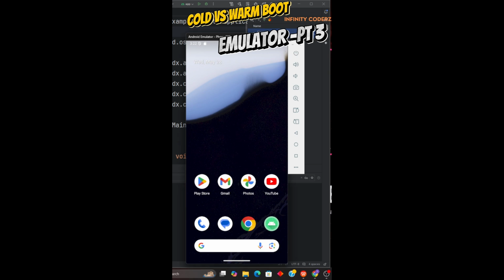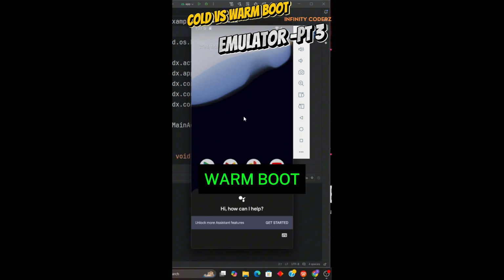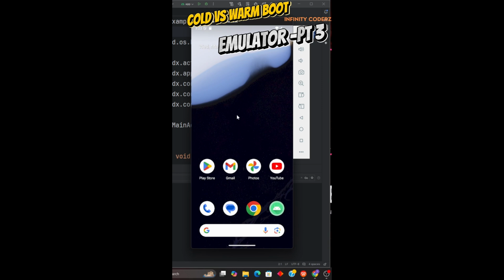So one useful tip is, you should only use a cold boot only when you need. Cold boot means that you will actually restart your entire process from the power up again. But if you use snapshot, what happens is you will power down from where you currently are, and then you will power up directly to the location where you previously powered down at. So this is much easier, and then you don't have to restart from a cold boot, right? So this will help you to process.